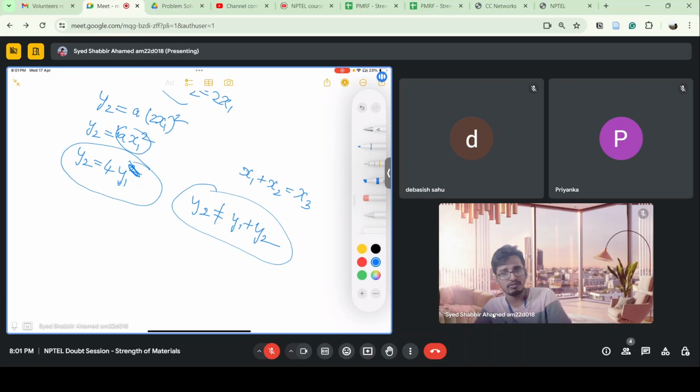It might be going to non-linear zones and all. Sometimes you cannot restrict the load to only linear things, because if I want the structure to remain linear, let's say I have a small beam and I apply a load, and it is having plastic deformations, but I want this beam to remain an elastic beam, what I'll do is increase the dimensions. I'll make the beam very big so that it is resisting more load.